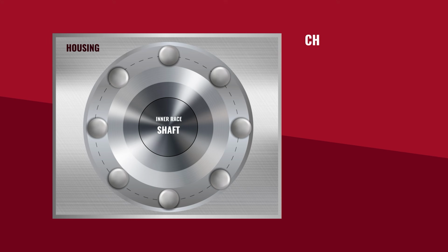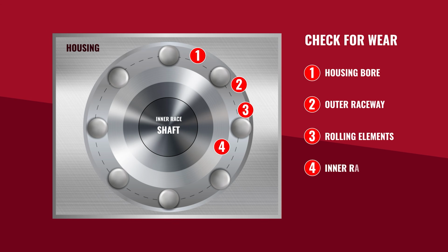So you need to check shaft and housing to make sure that they are clean and there's no wear apparent. If there is wear apparent, you need to change the housing or the shaft, whichever the wear is on.